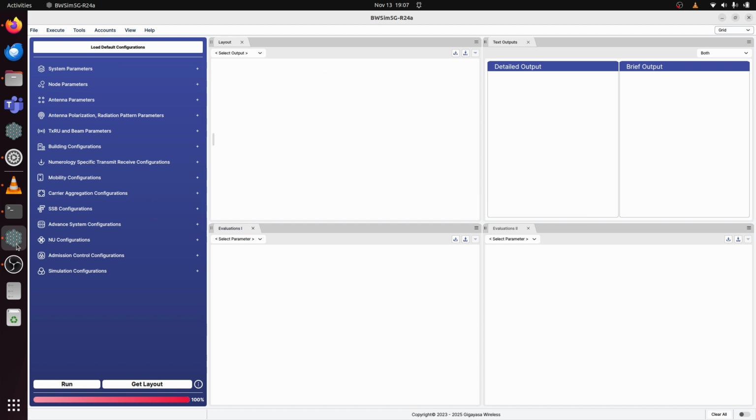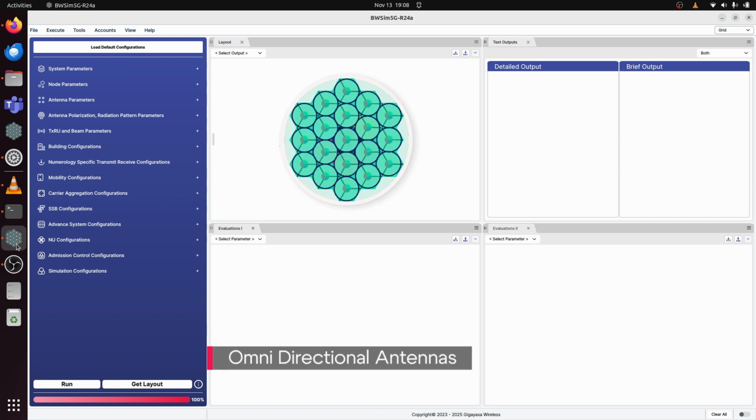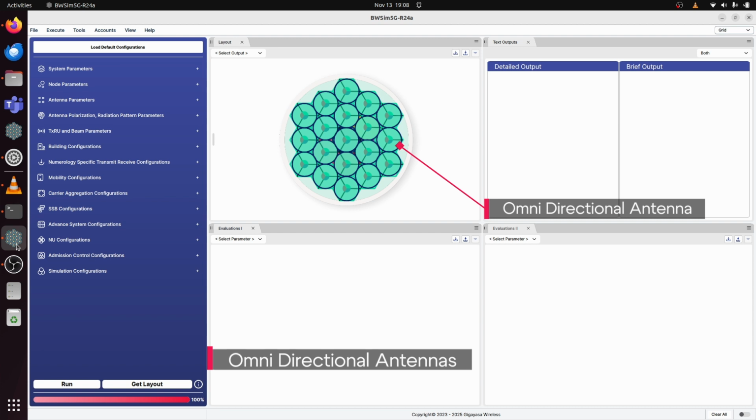Let us move on further to the geometry of cells. When we are diving into FFR and RF planning, it is crucial to have a solid grasp on what exactly will be the radio footprint of a base station, which in turn leads to the shape or geometry of a cell. What we have used earlier are omnidirectional antennas. These were the go-to choice for coverage. These antennas cast a circular coverage pattern in the azimuth plane. It's like a signal spreading out evenly in all directions.